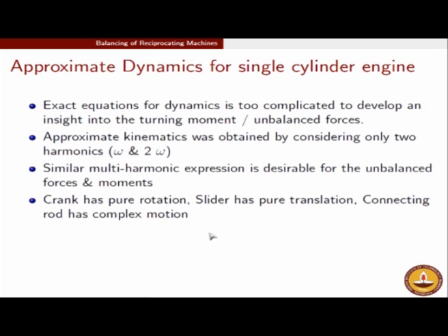It is just one notch a little more difficult to visualize than the crank or the slider. The crank motion is easy to visualize, it is undergoing pure rotation about the crank pin. Similarly, the slider is easy to visualize, it is only reciprocating within the inner walls of the cylinder, whereas it is the connecting rod which will undergo both rotation as well as translation. So, that is a little complicated to visualize. It is in fact this connecting rod kinematics which is making things very difficult for the exact analysis.